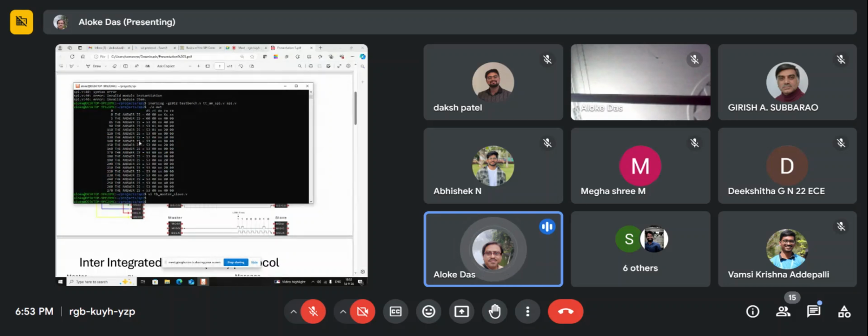These are also very important. This doesn't add anything to your design, but it adds a lot of value to your verification. This is the very basics, a very primitive kind of verification. So I am adding data in, then clocking in, and I get some output, and I check. I know what should come, how it should come, and when it should come, and I'm verifying that at all the time stamps.